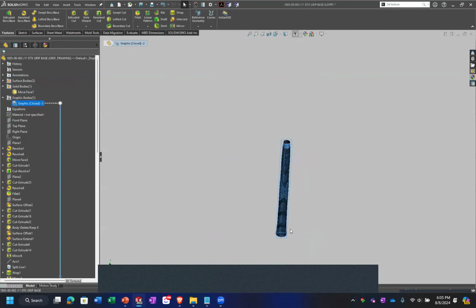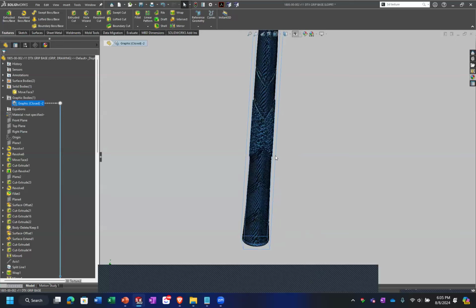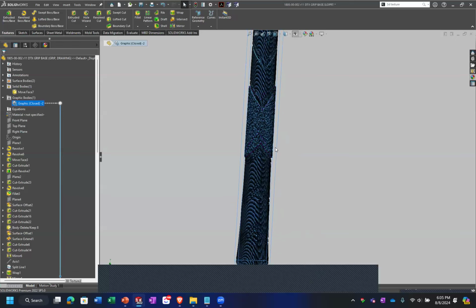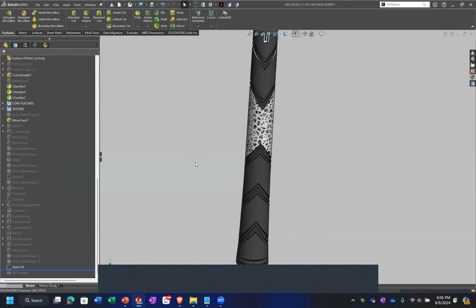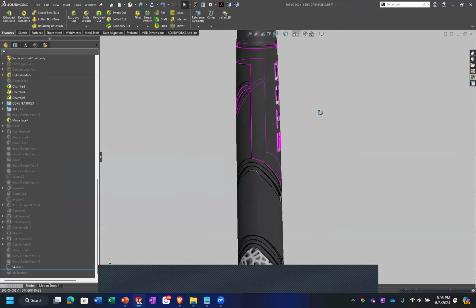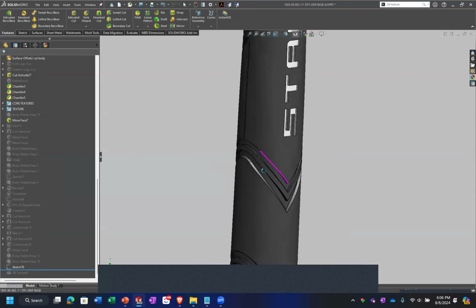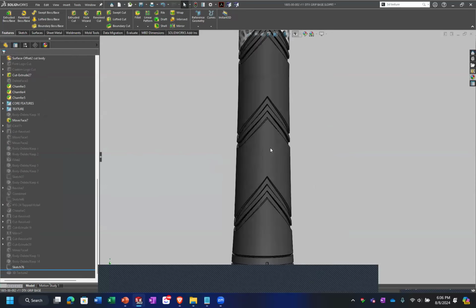So it's not a real SolidWorks watertight body when you add that graphics feature and texture. Theoretically there are some ways to hack around it, but essentially that texture you want to be the last feature in your model. You don't want to apply a texture and then do a revolve or something. That's not going to be a good workflow. You really want that to be the last item in your feature tree. And a lot of times you'll either suppress it or just roll above it when you're doing other things, because that is not a feature you want rebuilding the whole time.